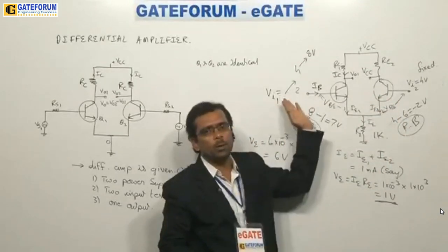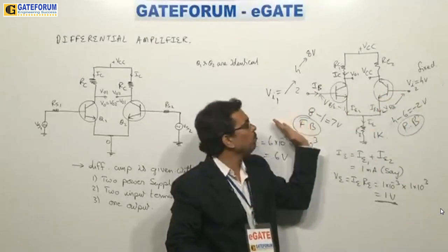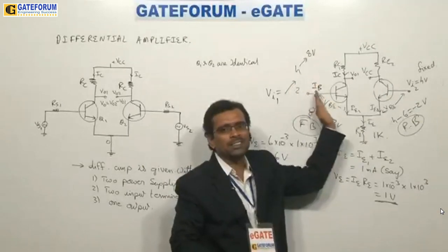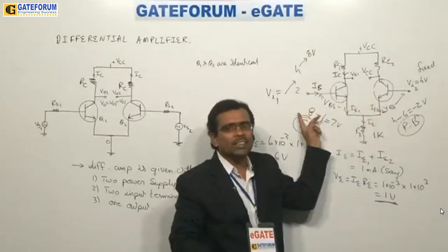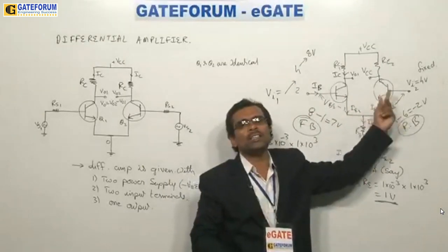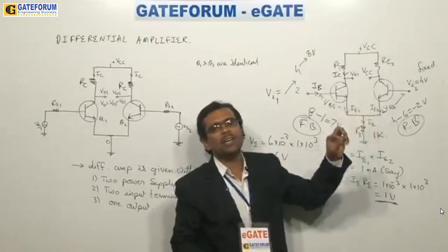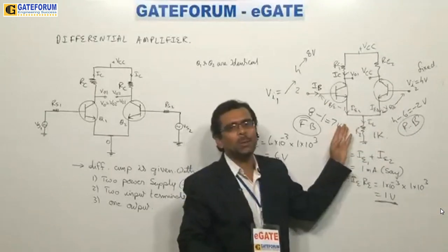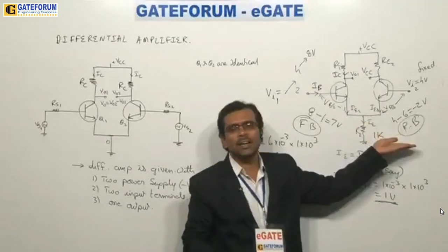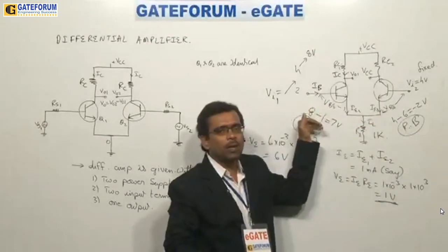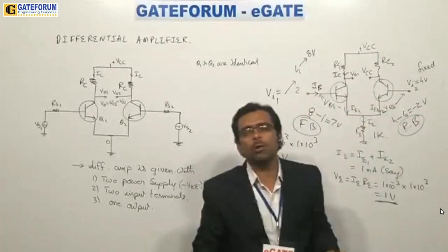This is operating its own inputs, and this is silently sitting with a fixed value. But what happened? You see, when I try to change the voltages at this transistor, immediately this transistor has gone to cutoff region. Without touching this transistor, I am able to operate this transistor's functionalities also. That is the greatness of this circuit and the weakness of this circuit also, because I did not expect this output, but it is giving me the wrong output. I did not ask this transistor to go to cutoff, but I am operating only with this transistor, and this transistor output has gone to cutoff. That is the point you need to observe.